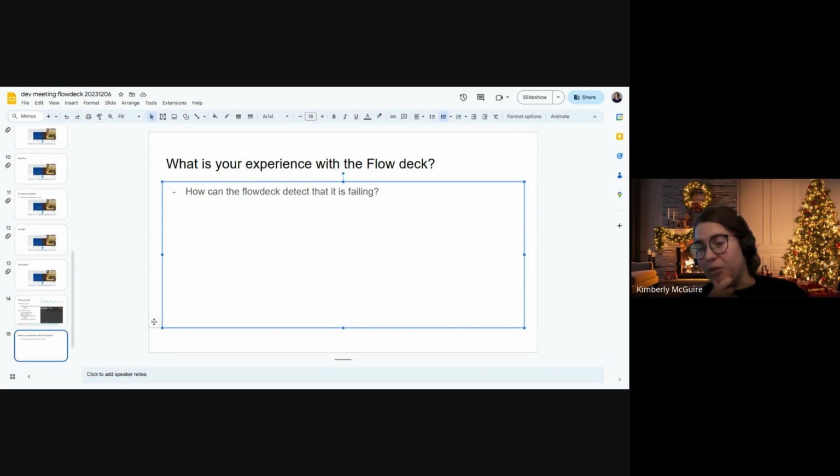I guess, Pascal, you mentioned that you're going to be looking into fusing, for instance, the multi-ranger sensors with the position estimator, and that's also a good way to solve that issue. Because then you don't have only one value of the velocity, but you can also use, for instance, how quickly you're going towards the walls. You can merge that as well. That's the whole principle of SLAM and localization. So those are ways to solve that.